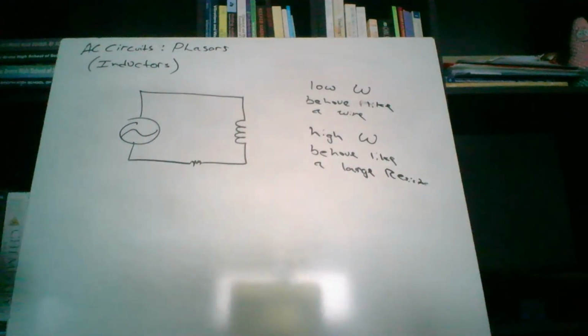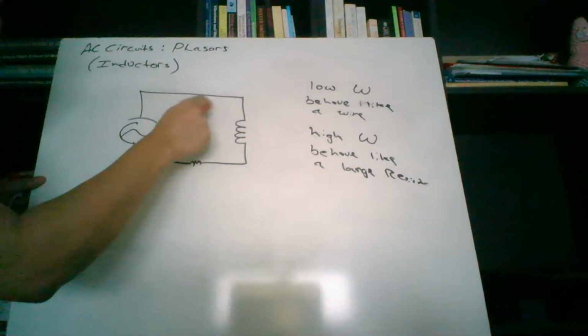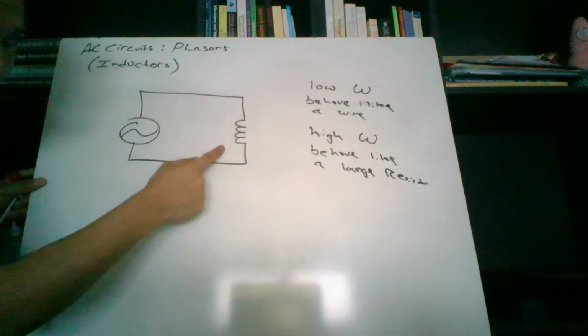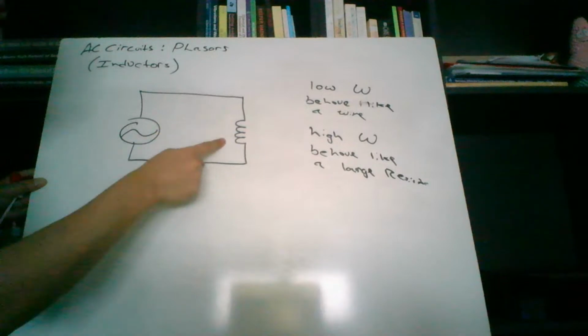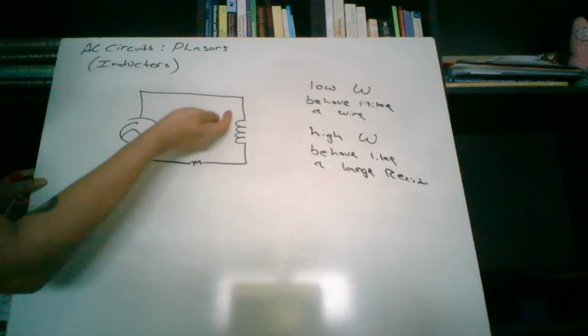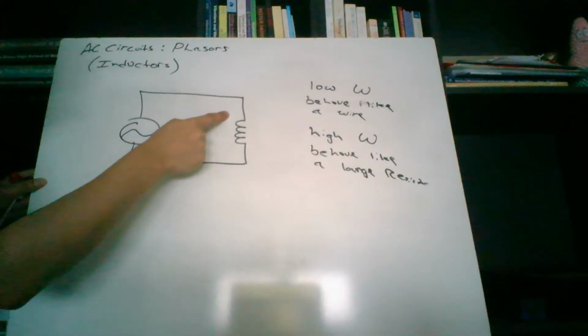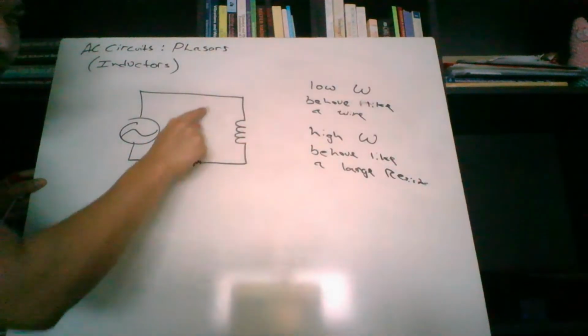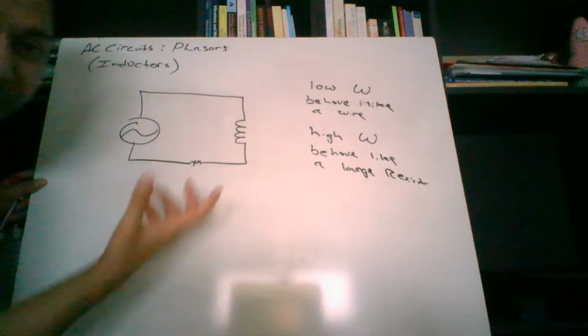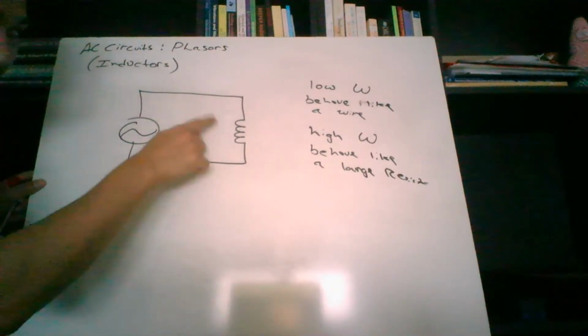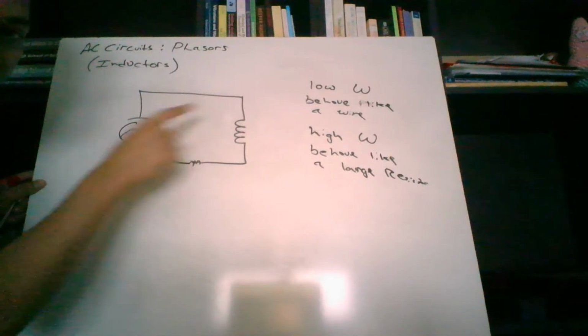And we knew this. So if you slowly allow current to go through here, eventually all the current's going to go through here, and it's going to behave like a wire. And then you slowly push it out, then it's going to behave like a wire again over time. But if you change the current too fast, then you're going to produce a large EMF. You're going to create a voltage that's going to try to oppose it.